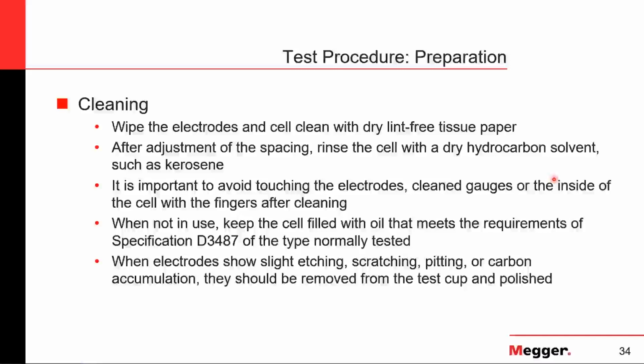Now for the sampling, we already discussed sampling in detail, but again, just to summarize, you need to review ASTM D923. On that standard, you will find the procedure we just reviewed, as well as recommendations to both sample from different type of containers when you get oil directly from a supplier, and also details on the containers recommended for each type of test in the oil.